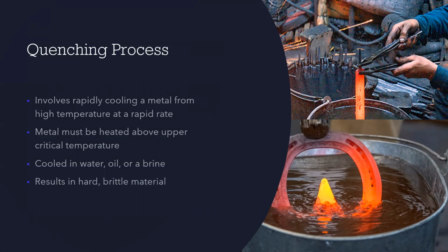However, if the quenching process is done too quickly, there is a possibility of bending or cracking your specimen. Here you can see I included a few examples, one being someone quenching a knife and the other quenching a horseshoe.